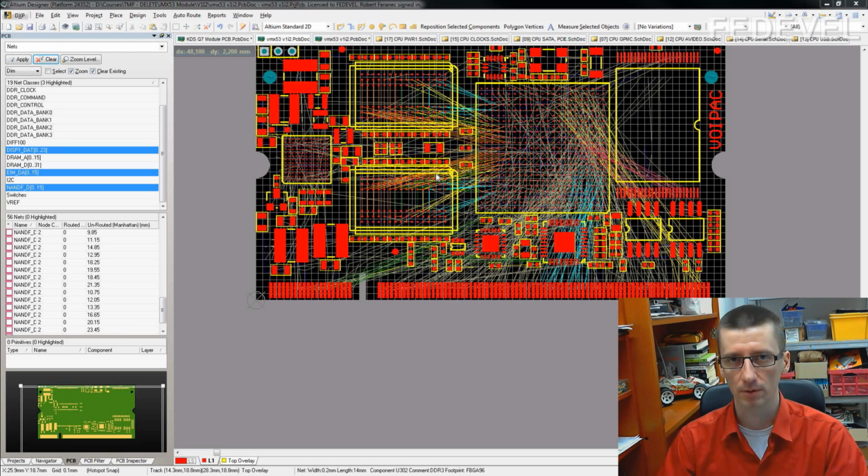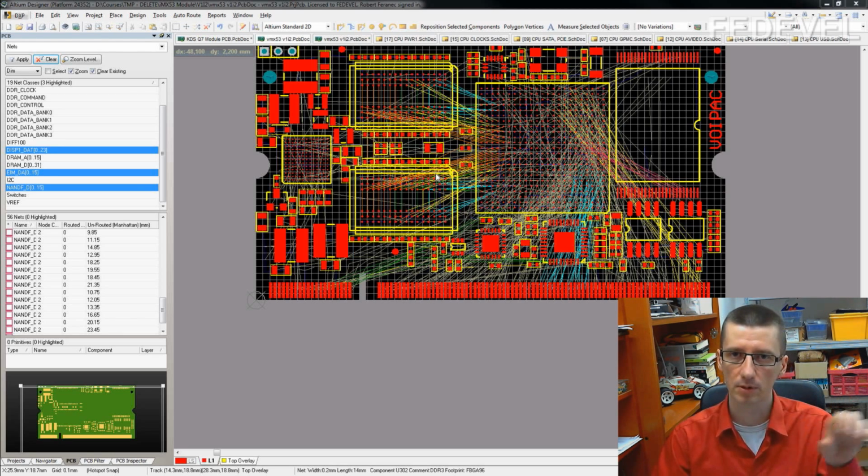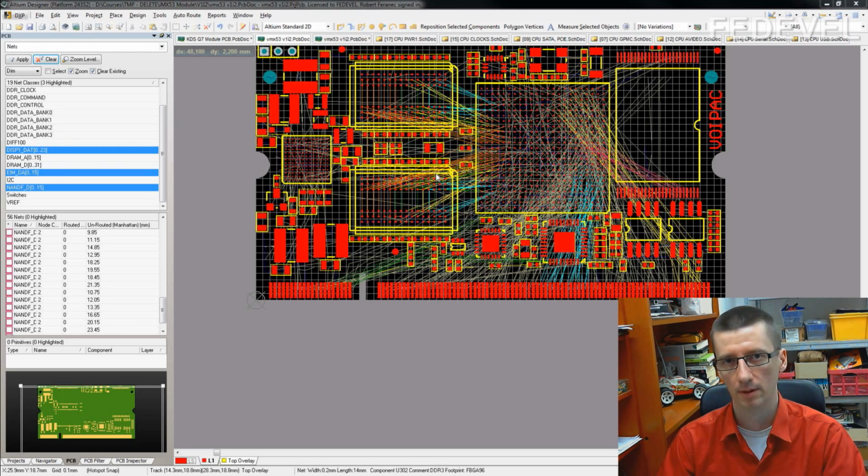What I normally do, I have a look if there is no other really difficult BGA. Normally there is, because there is usually a chipset, and that's the second chip I do after the processor, and I use exactly the same technique. So you can have, for example, processor and FPGA, and you can do the fan out for the second very difficult BGA chip.